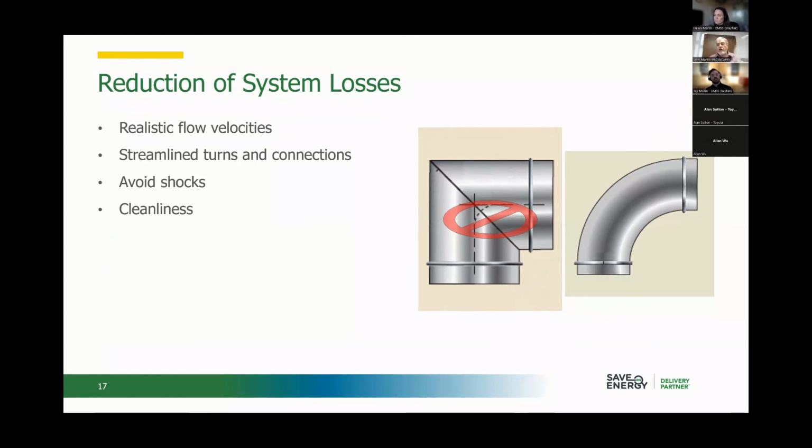And the other thing that often happens on inlets is they've got to put some kind of a screen on it in order to keep the birds and whatnot out. Now even this one here is not going to keep mosquitoes out and whatnot. That's for the filters, I guess. But this one here is what we call expanded metal. And I've seen this used out there instead of having fairly light duty screens that are still heavy enough that they would keep birds out.